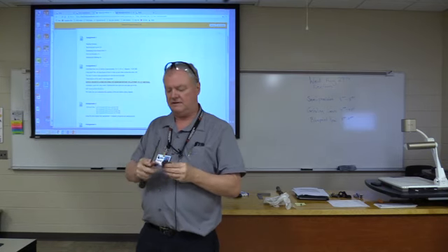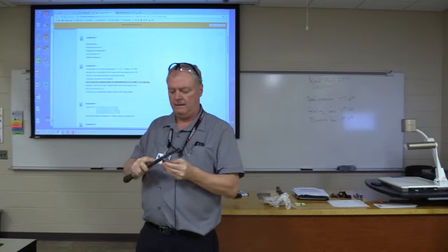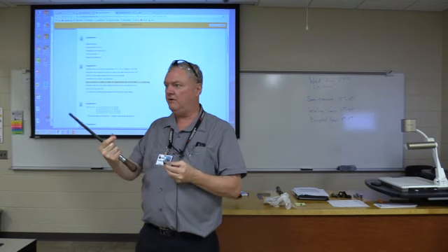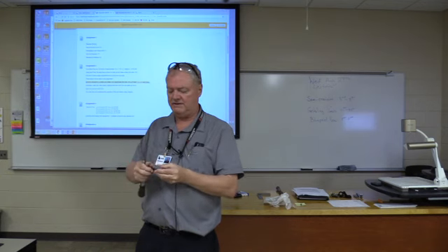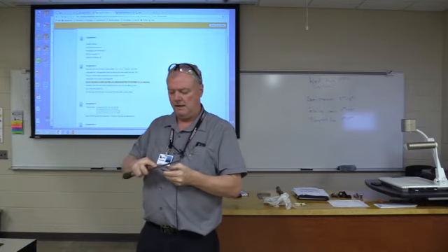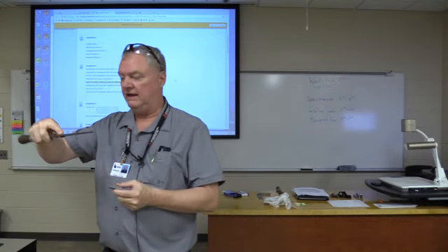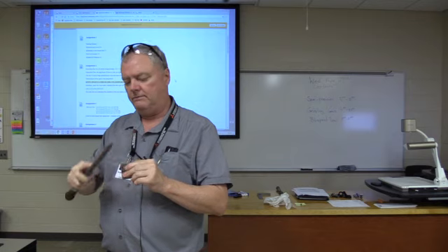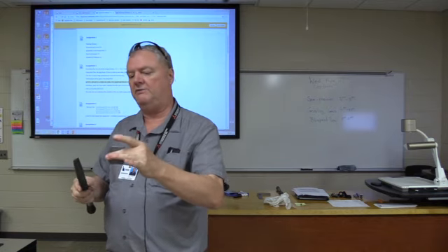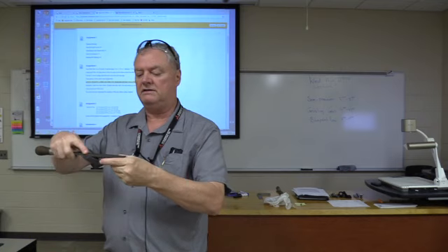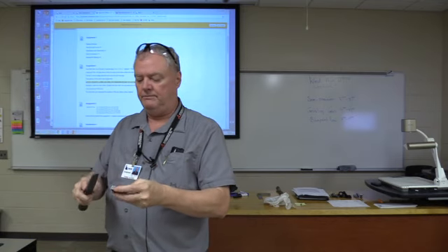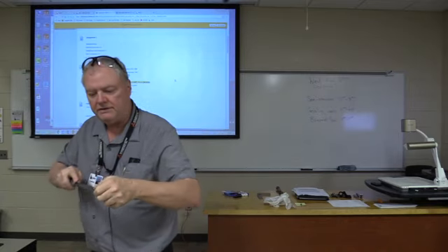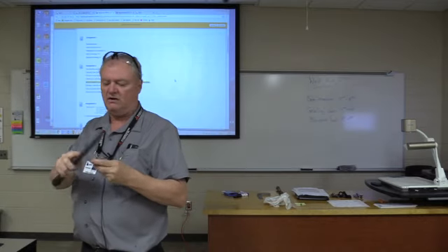The other reason you do this is because this burr, if you're going for precision machining and trying to hold a tolerance, you can't have a burr in between the part and where it's sitting. You always have to be free of burrs, and then you're going to be guaranteed the part's going to lay flat and soundly against any work-holding device you have. Pretty much the way you use a file, you're going to need to put it in the vise to do the surfaces, and you'd be using it like so, okay? Standing and taking a good solid stroke with that thing in the vise. But I'm just knocking off the burr right now.